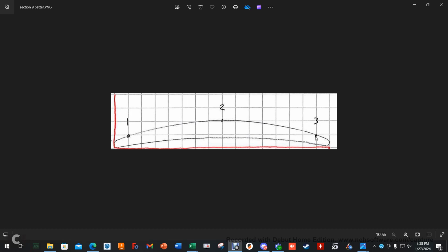If you want to know more, go ahead and YouTube it. There are some great videos that show how to do it and the theory behind it. Okay, so what would be the purpose of that? Well, the purpose is that I would like to get the inner area of this surface right here. Because if I can find that, then I can use it for my force analysis by finding the second moment of inertia, using it as the cross-sectional area.